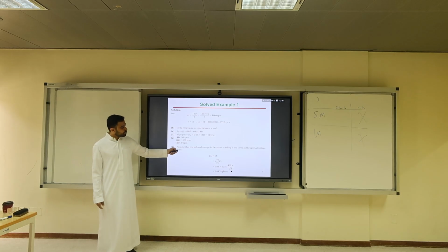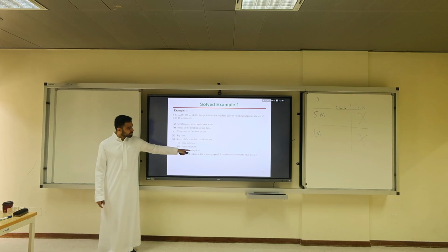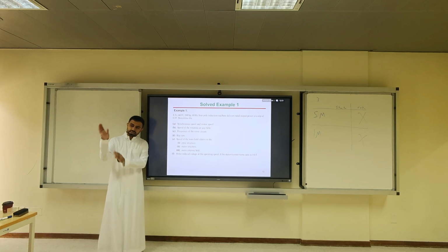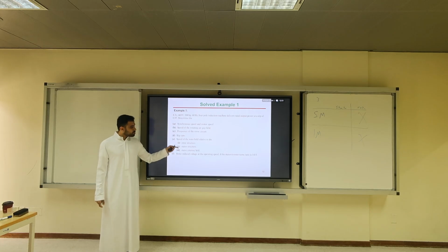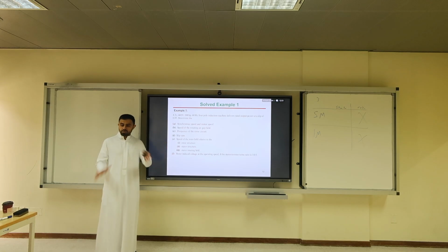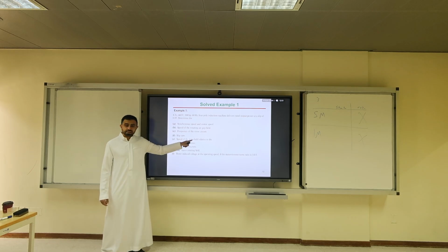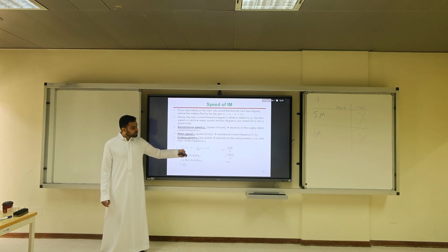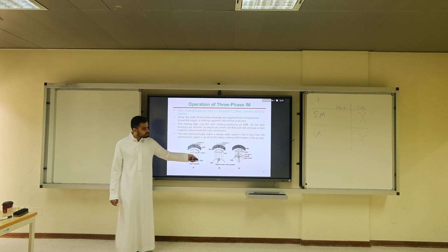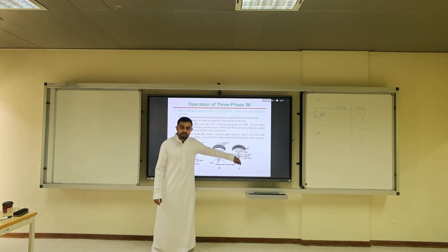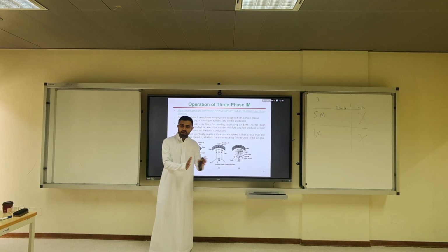So relative to the stator rotating field, it is the same. But with respect to the stator, it is synchronous speed because the stator is fixed. With respect to the rotor, it is the slip. Remember, he's talking about field, not current. This is field. The rotor field is the summation of whatever fields go inside the rotor. It rotates.